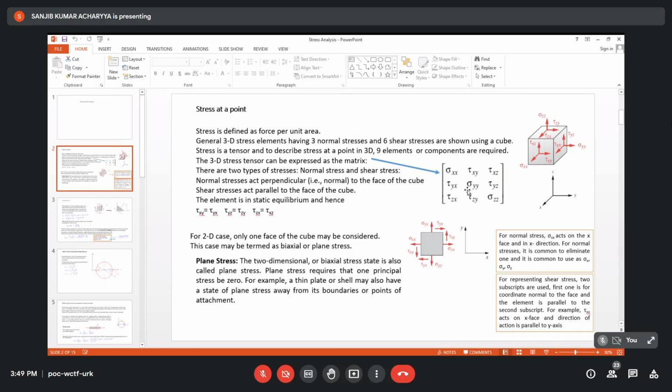Yes, sir. Therefore, load is to be converted into stress. When stresses are complex in nature, normal, shear, etc., then one kind of stress alone cannot answer your material failure point, whether it will fail or not. Because whether a member will fail under an axial load of 100 newton depends upon whether any other kind of load is present. If another kind of load is present, then at what tensile load it will fail depends upon the value of the bending load at that moment. It is related to the presence of bending load, isn't it?